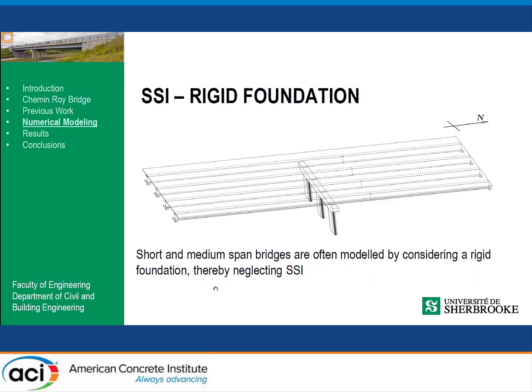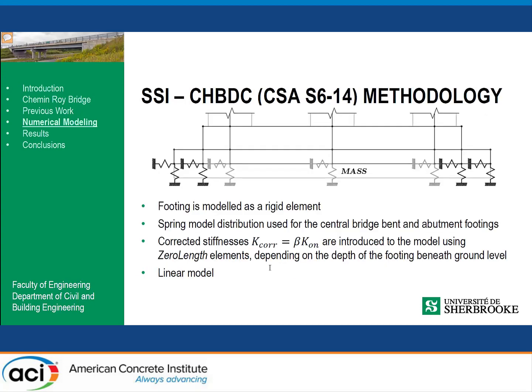Like I said previously, short and medium span bridges, at least in Quebec, which is a low to moderate seismic region, we often model by considering only a rigid foundation. But in this project, we decided to compare this response to two models considering SSI.